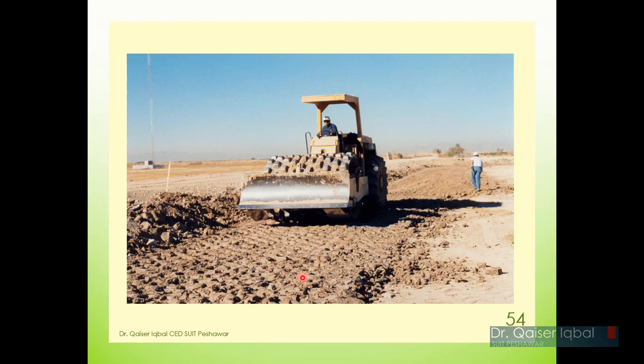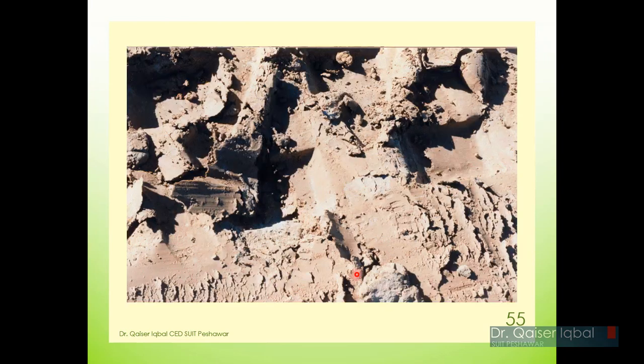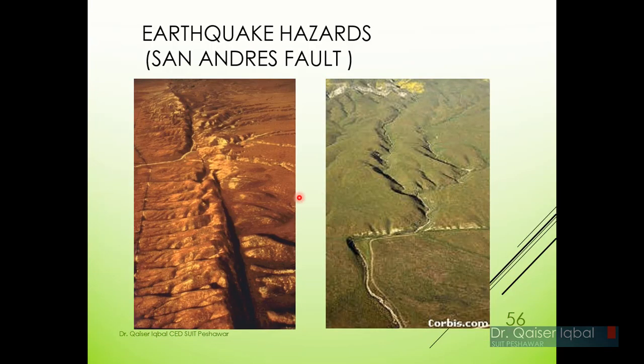The refinery building or any chemical plant or any other plant which will have hazardous material should have a clay cap, okay. So this clay soil will prevent the ingress, the entry of harmful substances into the ground from any leakage on the surface, okay. So this is also a very important application of geotechnical engineering. Here you can see a close-up of the clay, okay, being compacted by the sheep foot roller.